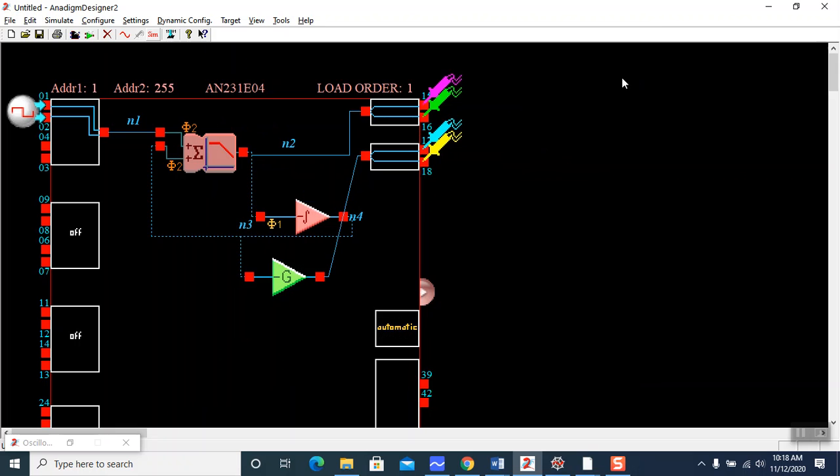All right. Now it goes through the inverting integrator, and then it gets summed back in. Now this is the low pass node, and I just put an inverting gain stage so that you could see the high and the low pass filter.